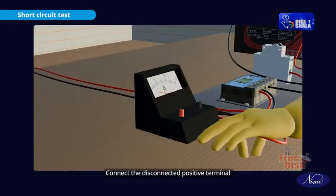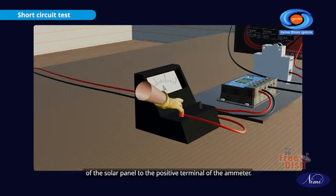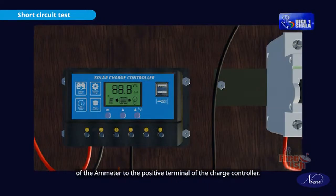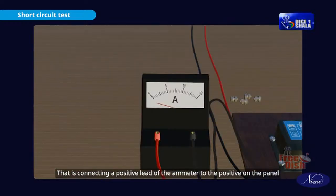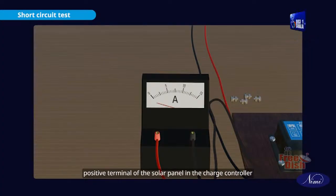Disconnect the positive terminal of the solar panel from the charge controller. Connect the disconnected positive terminal of the solar panel to the positive terminal of the ammeter. Now connect the negative terminal of the ammeter to the positive terminal of the charge controller. This connection puts the ammeter in series with the solar panel and the charge controller. That is, connecting the positive lead of the ammeter to the positive of the panel and the negative lead of the ammeter to the load via the charge controller.